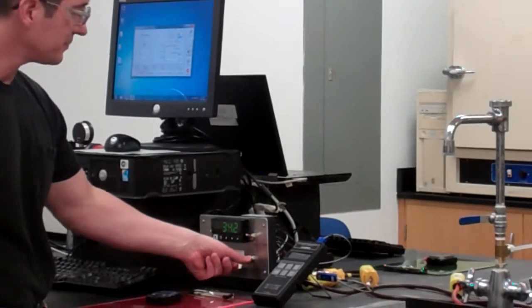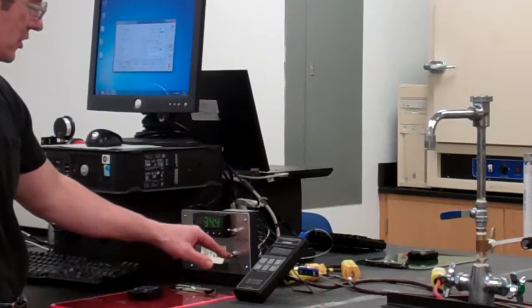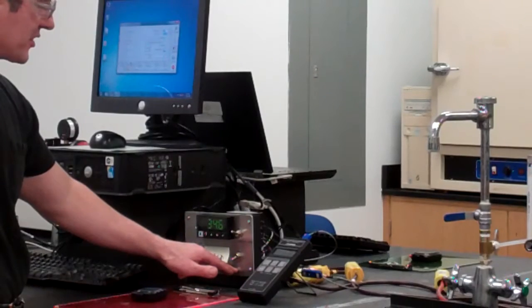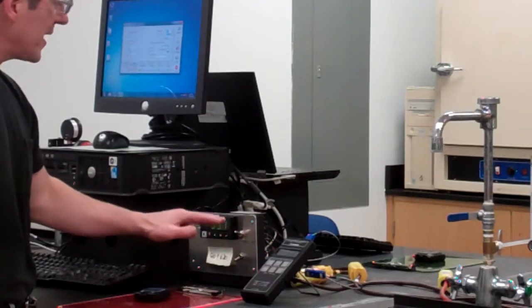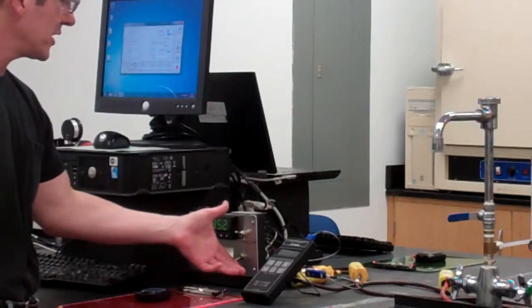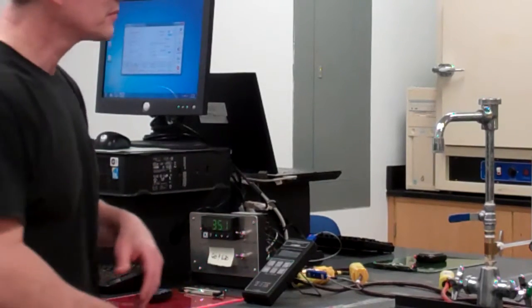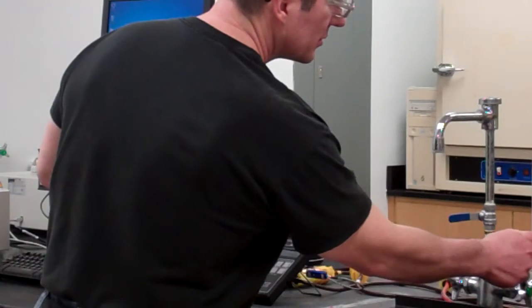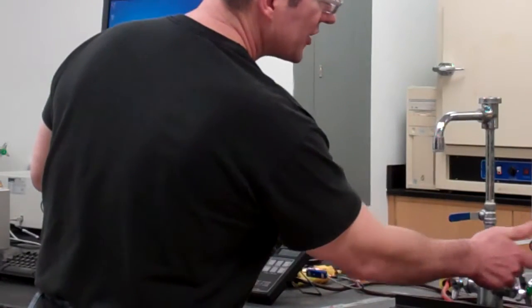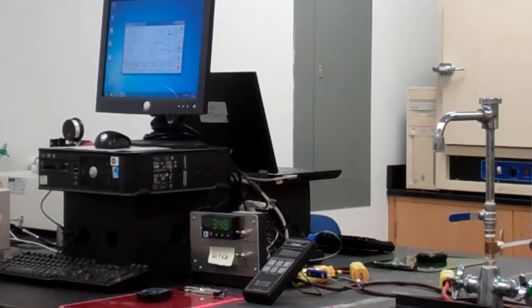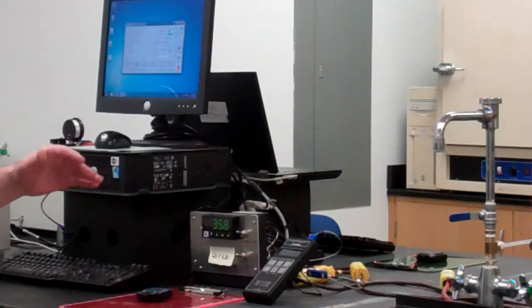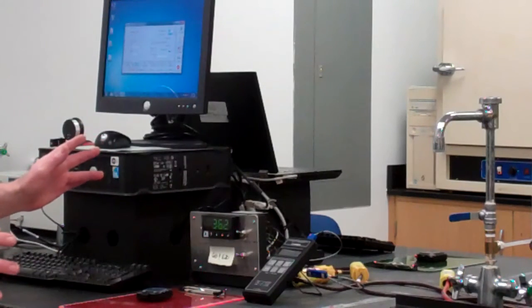You can always just turn the switch off. This is what connects the output from this device to the actual heater. And so if you turn that off, basically you've stopped sending output to the heater. So again, just be careful when you make the step changes, not to exceed the 60-degree temperature safety limit on this. So again, I know that's a lot of information in a short period of time.